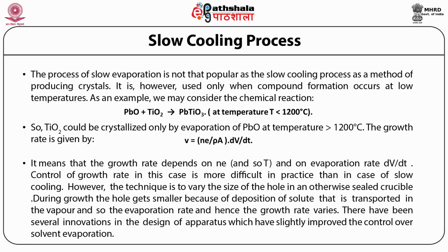However, the technique is to vary the size of the hole in an otherwise sealed crucible. During growth, the hole gets smaller because of deposition of solute that is transported in the vapor, and so the evaporation rate and hence the growth rate varies.